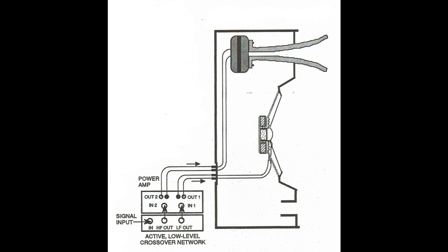This separated signal is then sent to the two amplifiers, one of which powers a woofer, and the other a high frequency speaker or driver. The tri-amplified systems use that same principle, except they split it into the low, mid, and then high frequencies before sending that signal out.